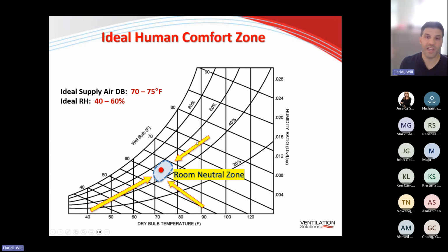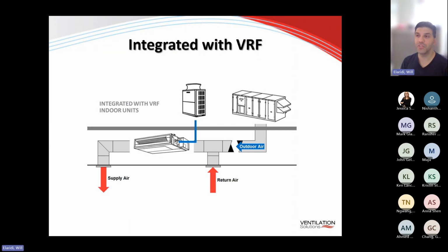So if it's too dry, you simply want to add humidification. And in the summertime, you can do dehumidification using the DX circuit here. Now, there are two ways of installing the DOAS system, which could be integrated with the VRF system, for example. One way is having a coupled or integrated system, which has the fresh tempered air being supplied by the DOAS unit directly into each fan coil unit. Some fan coil models allow for a 4-inch cutout, which allows fresh air into the fan coil while mixing in with the return air.